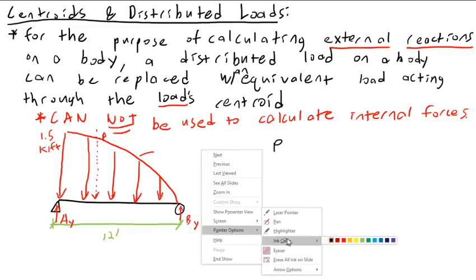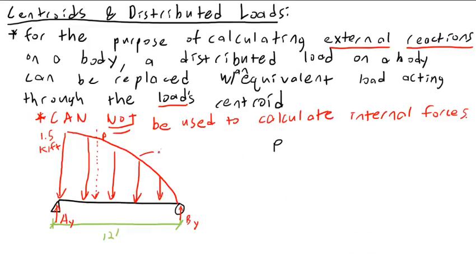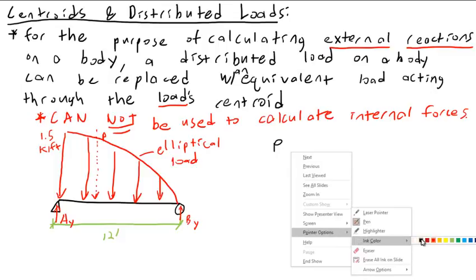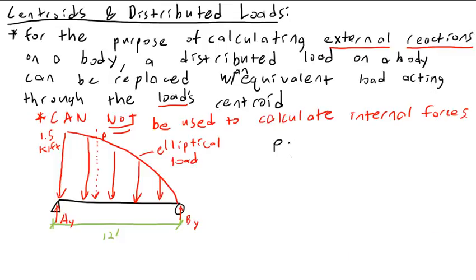No, it's an ellipse. Yeah, it has to be an ellipse because they're not the same unit. So elliptical load. That'll make a little more sense. I can live with that. So let me go to the table and find the formula for the area of a quarter ellipse. Pi AB over 2. Right. Let me see that. Area pi AB over 4. Yes, pi AB over 4. So here, the formula for the area of a quarter ellipse is pi AB over 4.